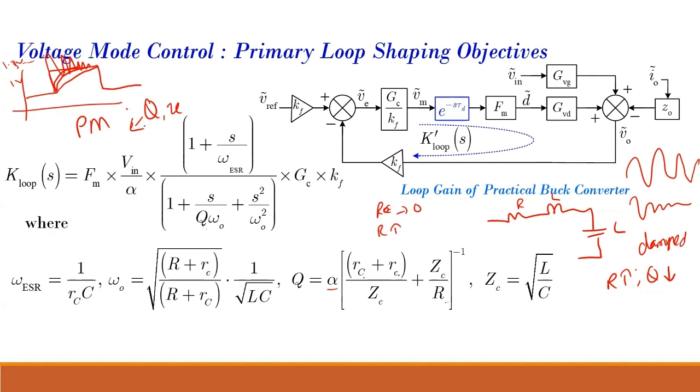But it is observed practically that as your phase margin is increased, your zeta increases, and your system gives a better damped response. For a second order system you have an exact formula which you can use, but for higher order systems it is intuitively observed that as you increase phase margin, it is more damped. But you'll have to see and try to understand.